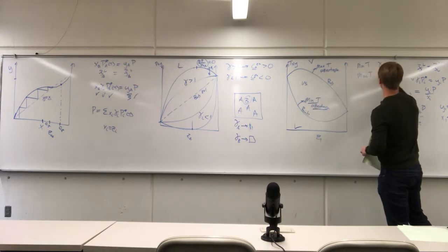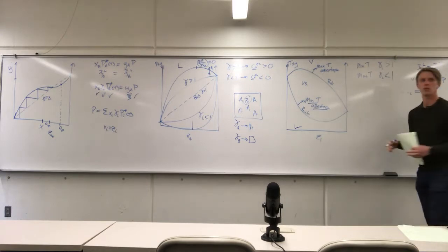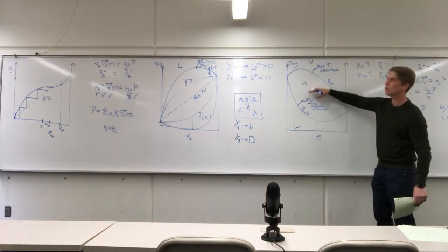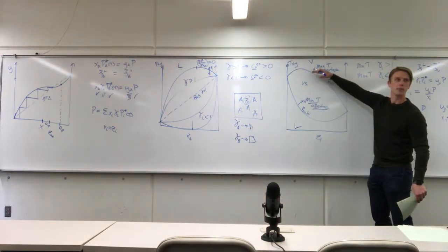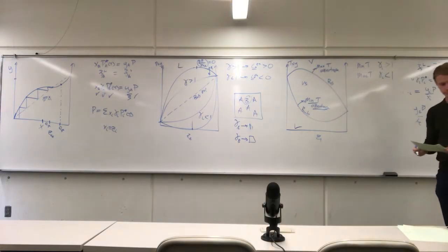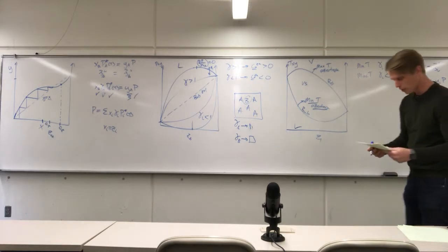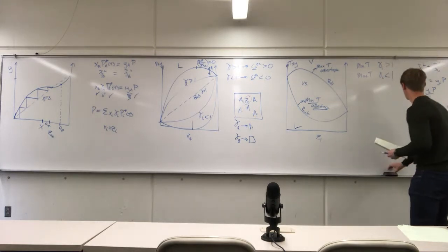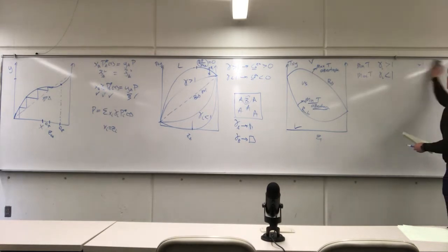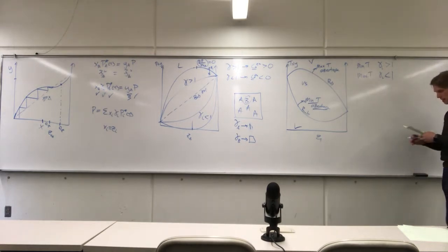For a maximum temperature azeotrope, your activity coefficient is going to be less than 1 because they're hanging on, they're actually having a really good time, and they're okay being a liquid mixture. And it takes a lot higher temperature to boil those two out. So one other thing that's very useful at azeotropic compositions is we can use them to benchmark activity coefficient models.